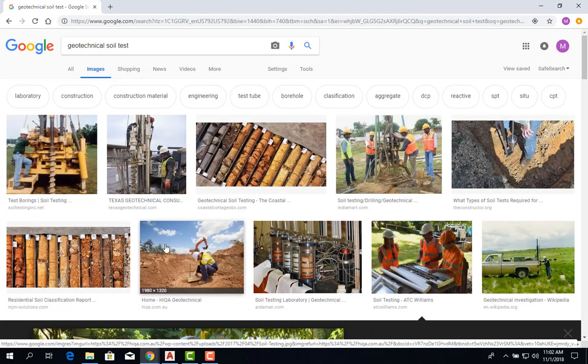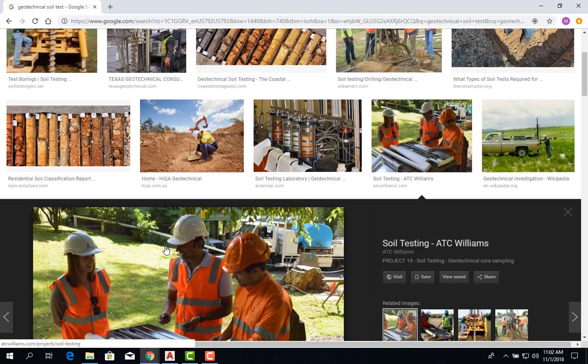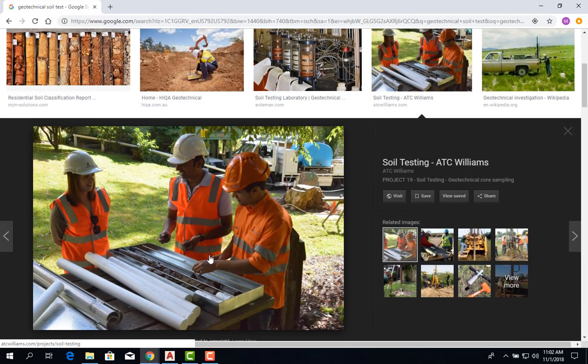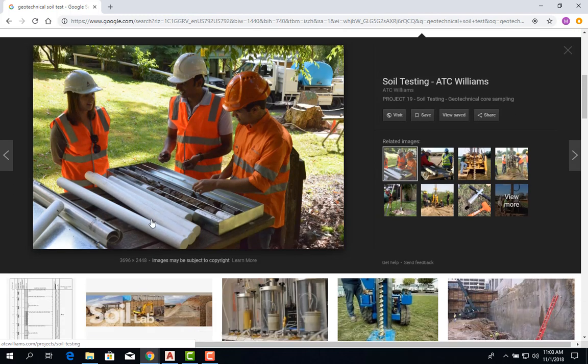And I'm going to show you some pictures of a church that we built, a church that I go to. We decided to have a soil test done just to be on the safe side. You don't want to put all that money into a building and then later on have your foundation crack because maybe there was something underneath. Maybe there was a lot of sand a couple of feet down, or there was a water table closer to the surface, which we're going to talk about next. So it's very good to have a test done.